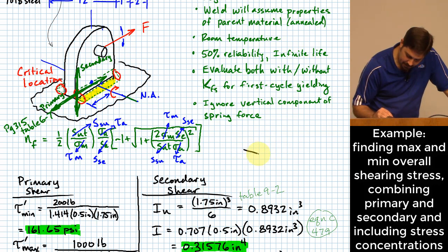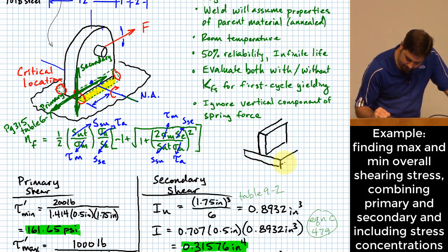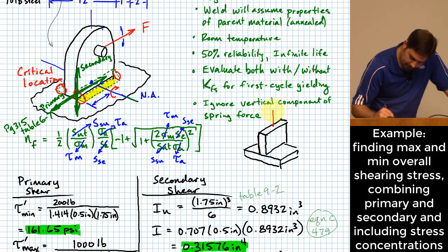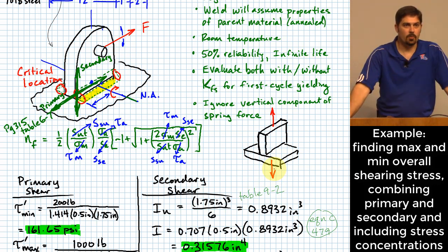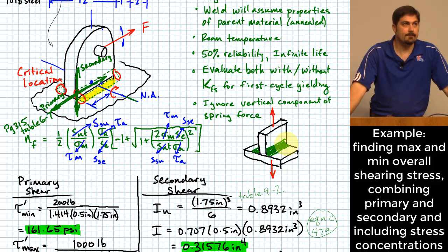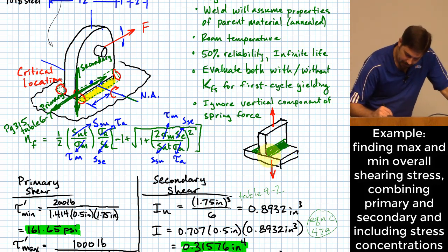Okay, if you have a T-butt joint, what that means is that you have a piece of material that's welded something like this relative to another piece of material. Right? Something like that. And it means that you're pulling on it like this relative to this piece of material. Okay? What direction of stress is induced in the welds that exist right here? Do you agree that the direction you're pulling on it will tend to stress the welds in this direction?